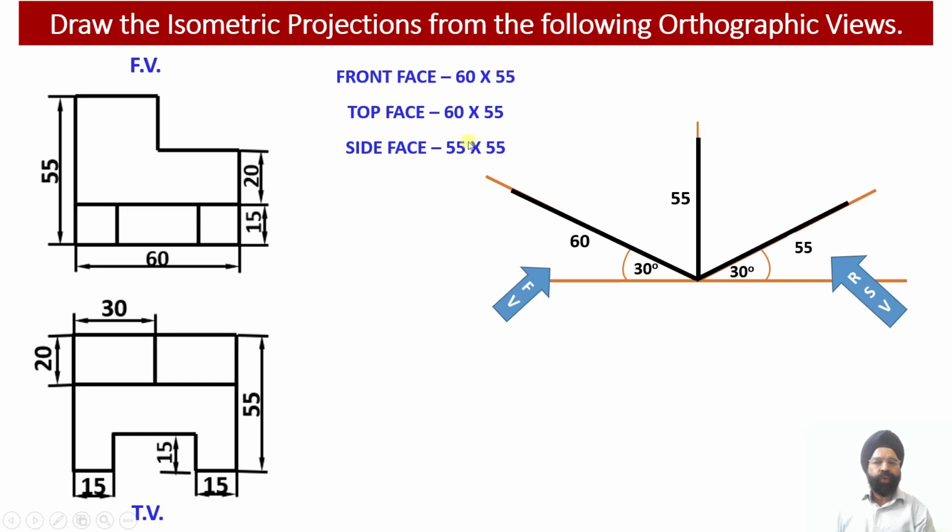Now we are going to locate the front view along the x-axis, and the width will be located along the z-axis in the isometric construction, because the vertical web we are going to draw on the back side, and this rectangular slot which we have on the front side of this horizontal web will be provided along the x-axis in the isometric projection.